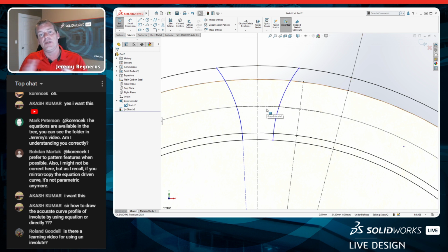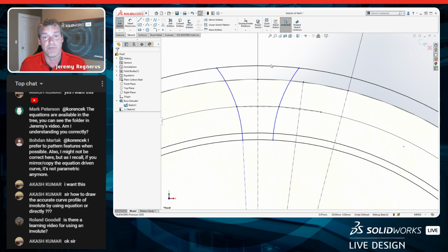This is now a known value that we can always come back and reference, or that we don't have to use a pi-driven equation. I will point out, if you want to add the value pi to any of your equations, you just type pi, and SOLIDWORKS will do the calculation for you. And it'll put the numerical value in there, I think out to 8 decimal places for you. So that is available in the equations as well. I'm doing these with relatively simple equations and letting sketch geometry control the rest of it for me.